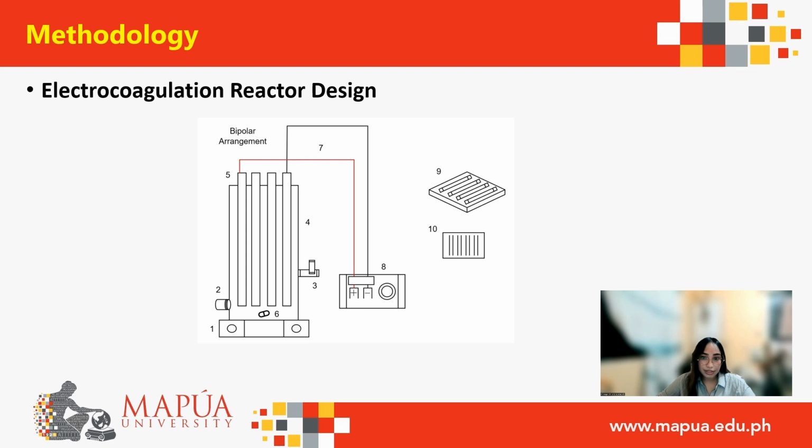For the EC reactor design, as seen in Figure 1, 3 liters of distilled water was used in a 3.86 liter glass reactor. All the electrode vessels have the same dimensions, 100 millimeters by 100 millimeters by 400 millimeters, with an electrode spacing of 16 millimeters, immersed in the solution using the aluminum and iron electrodes. To ensure the electrical conductivity in the reactor, the bipolar electrodes were linked in parallel. The iron and aluminum plate electrodes measuring 80 by 500 by 2 millimeters were used in all EC operations, submerging 300 millimeters of length in the solution.